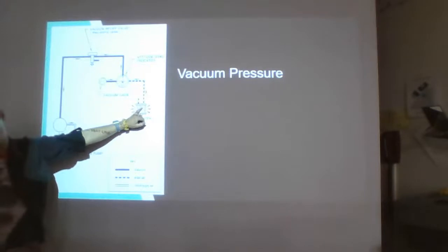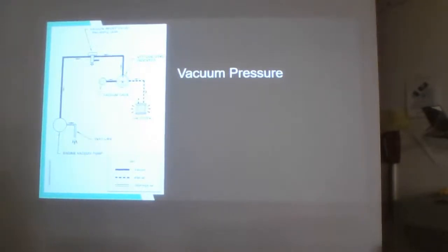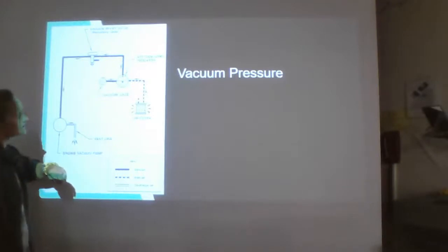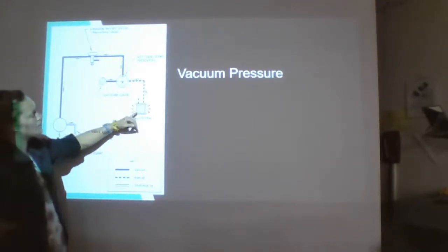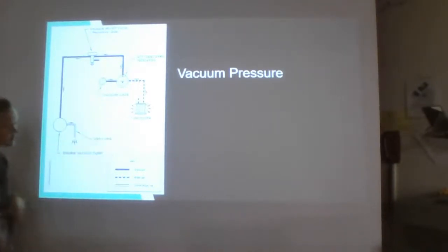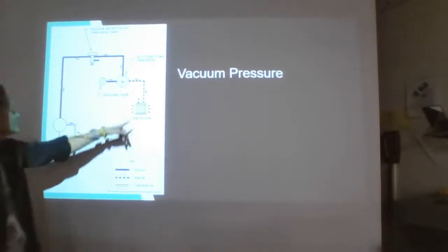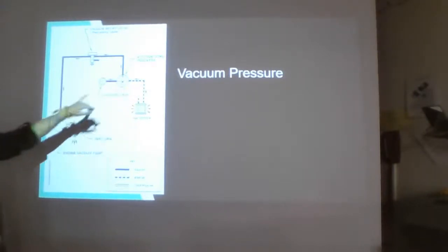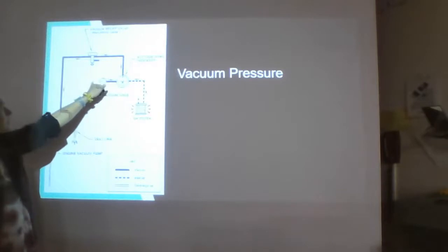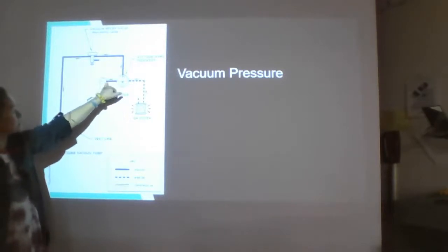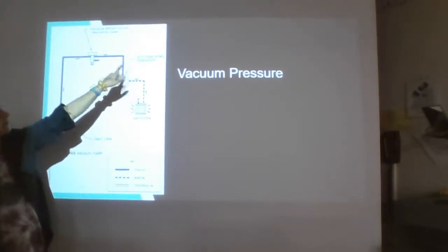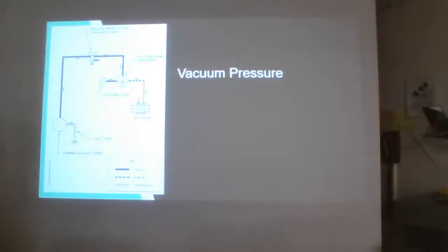We want our instruments to have clean air, especially our vacuum instruments, especially our gyro instruments, because they depend on that air so much. So our incoming air is filtered through our instrument air filter, is sent to the vacuum gauge, and then operates our attitude gyro indicator in this diagram.